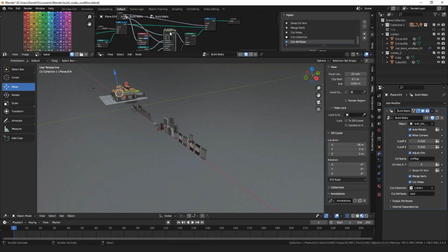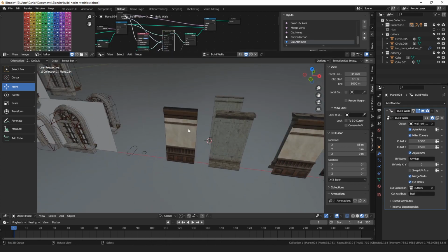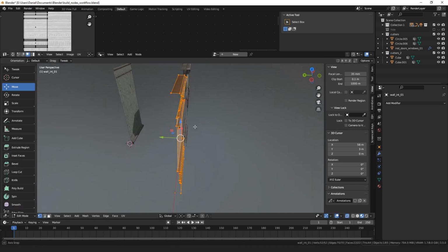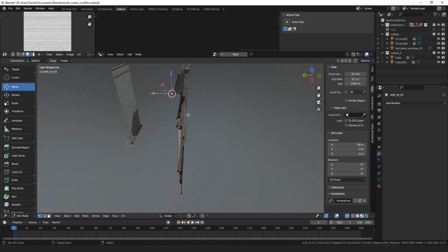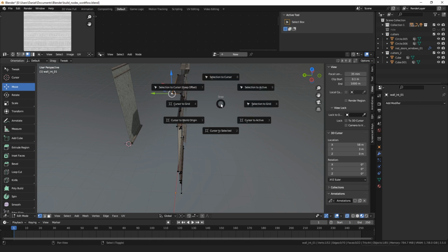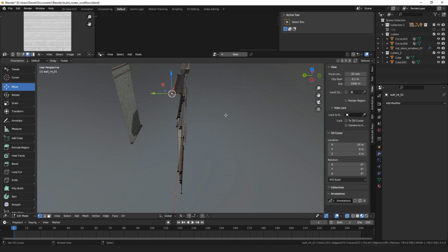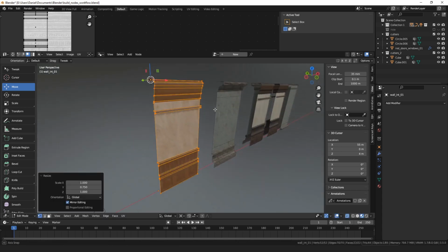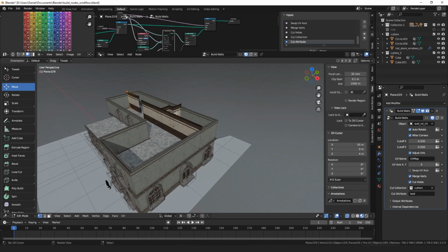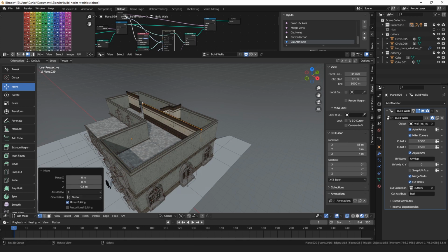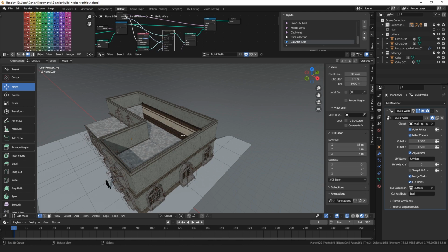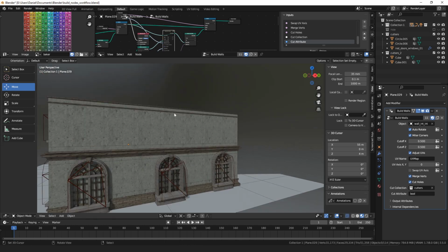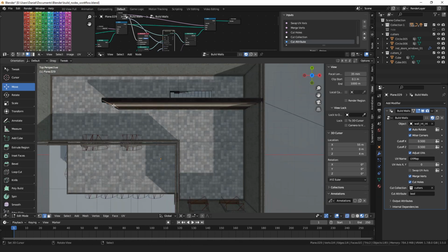Before I do that, so I can edit it, I'm gonna mute the boolean. So I'm just going to snap the cursor here. Select everything and scale it on the y-axis by like 0.75 or something. So then this wall needs to come down by 0.5 meters, since our second story is now 3.5 meters tall.